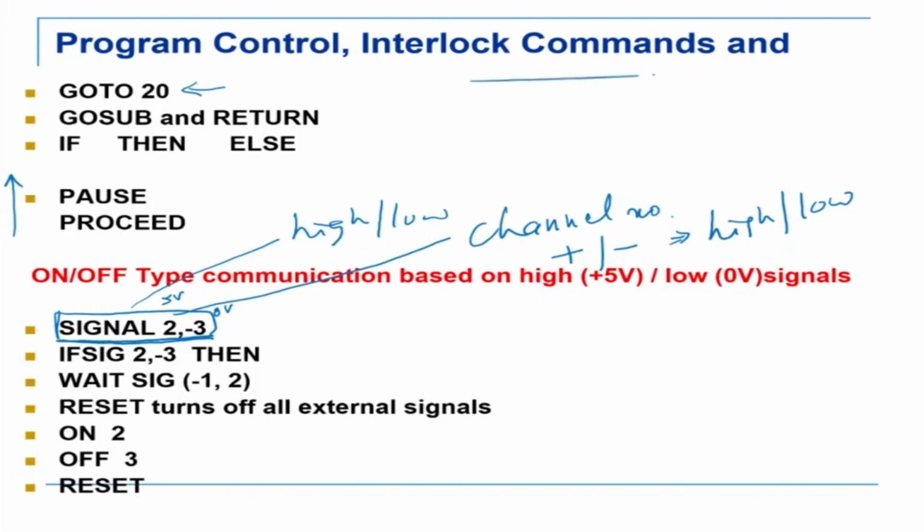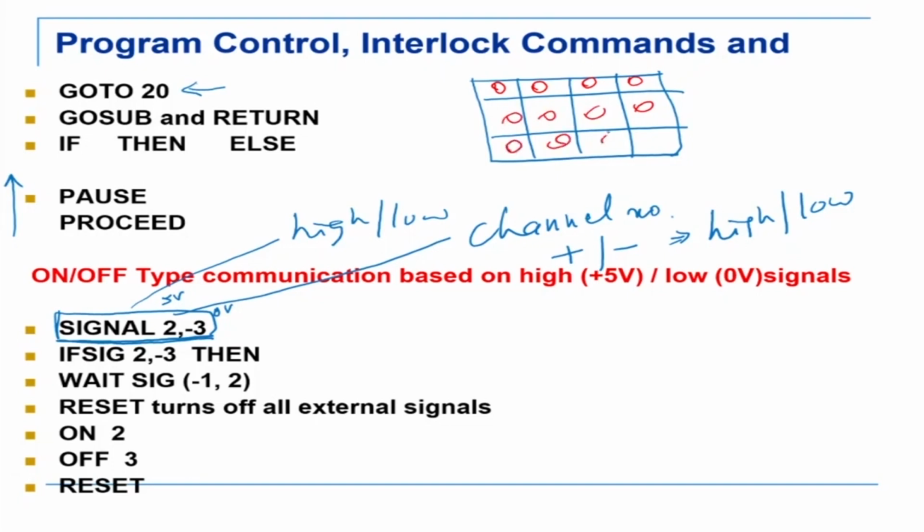So what I mean is, this is my indexing. This is the pallet, for example, where it is keeping. So it has to keep in all of these places like that. Basically, it will come here. It's a coordinate, right? It's a position coordinate. And these coordinates are fixed in this direction or this direction. So all it needs to do is, if I define this point, let's call it P1, then next time I just increment P1 by the distance here, which is, let's say, del x. And it moves to the next one, next one, next one, like that.